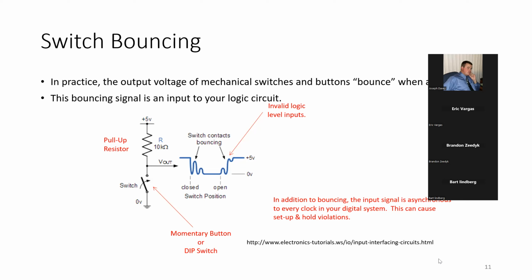And when it reaches the final destination, due to the spring, it contacts, then disconnects momentarily, then goes back and contacts again. And that is happening here in this figure. You can see this oscillation. The switch is closed and it is bouncing between contact and no contact.